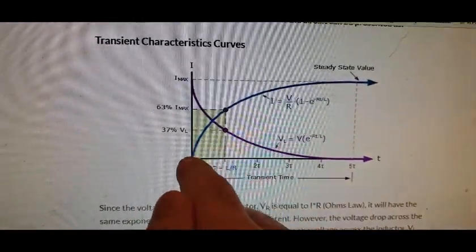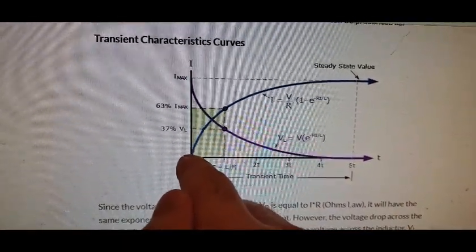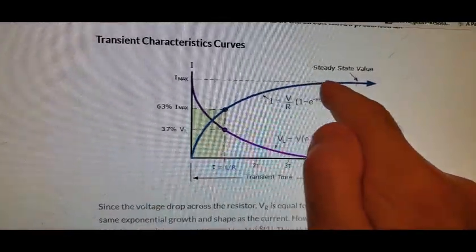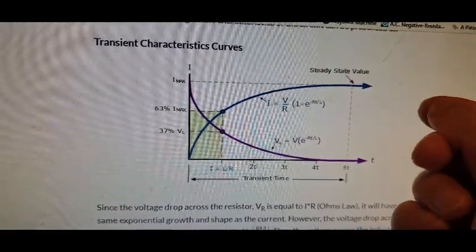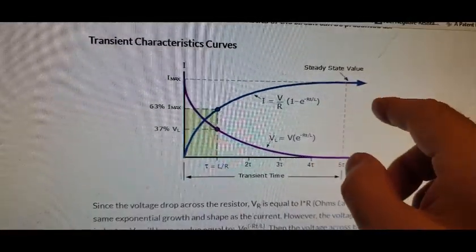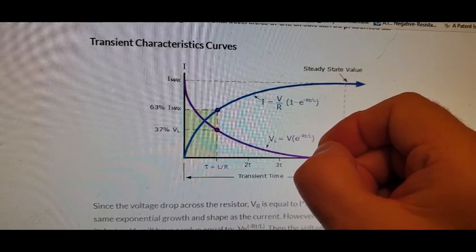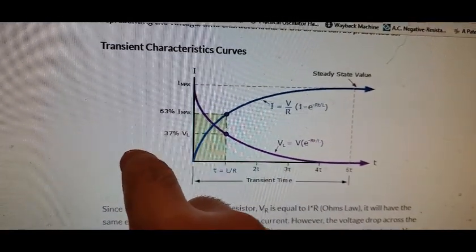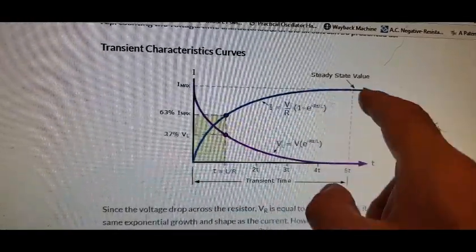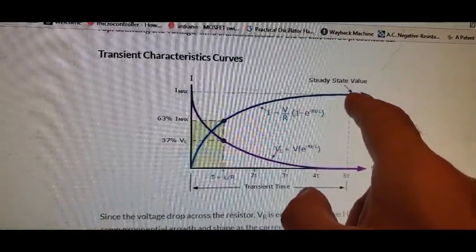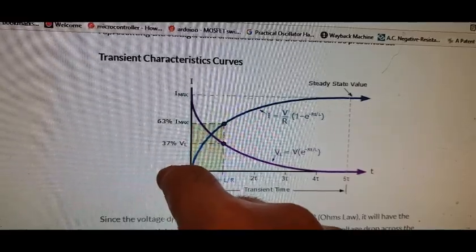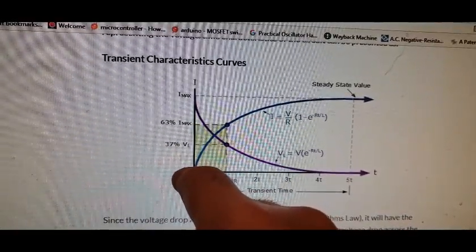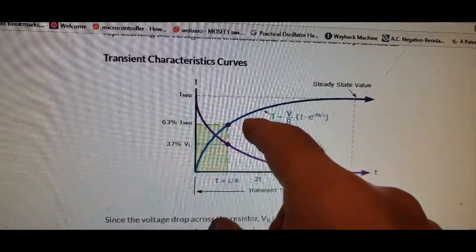And what you see here is the resistance is initially just incredibly high, and then it decreases until finally, when you get to the steady state, the only thing you have left is the straight line DC resistance of your wire. Now, if you're pulsing a cap into here, then you just added a whole other layer of complexity, haven't you? Because now the voltage isn't constant, the voltage is decreasing.